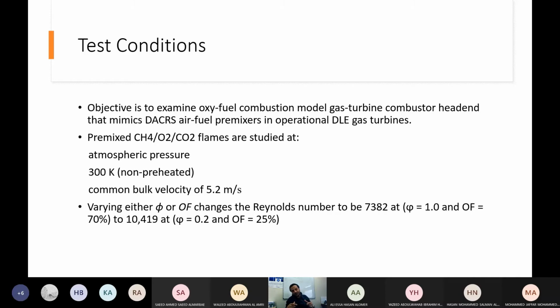And those actually are limited in the gas volume. So after some time, maybe two sets of experiments, we have to replace the cylinders again. So that's why, guys, we made the reactor size very small, but it is representative. It's a model combustor, a small combustor. The inlet area is small also. The inlet velocity is just enough to achieve a certain Reynolds number, so that we don't consume much gas. So we try to reduce the flow rate of gases in this case.